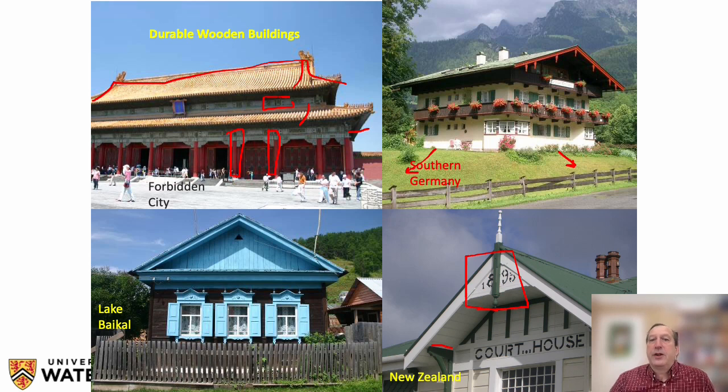This is a masonry building, but it uses wood. If you look here, these are wood roofs and wood balconies. And the overhangs, again, are measured in the meter, sort of a meter and a half, even 2 meters dimension, which means that the walls just almost never get wet. So it allows you to use a much less durable building material, or much less robust detailing, or much less skilled trades. You got all those options or some combination.